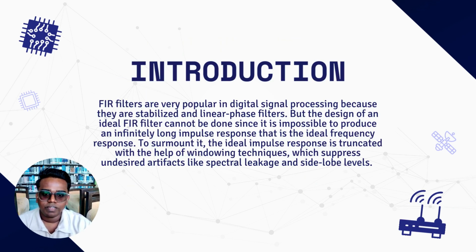The first part is the introduction to the FIR filter. FIR filters are very popular in digital signal processing because they are stable and linear phase filters. But the design of an ideal FIR filter cannot be done, since it is impossible to produce an infinitely long impulse response for an ideal frequency response.